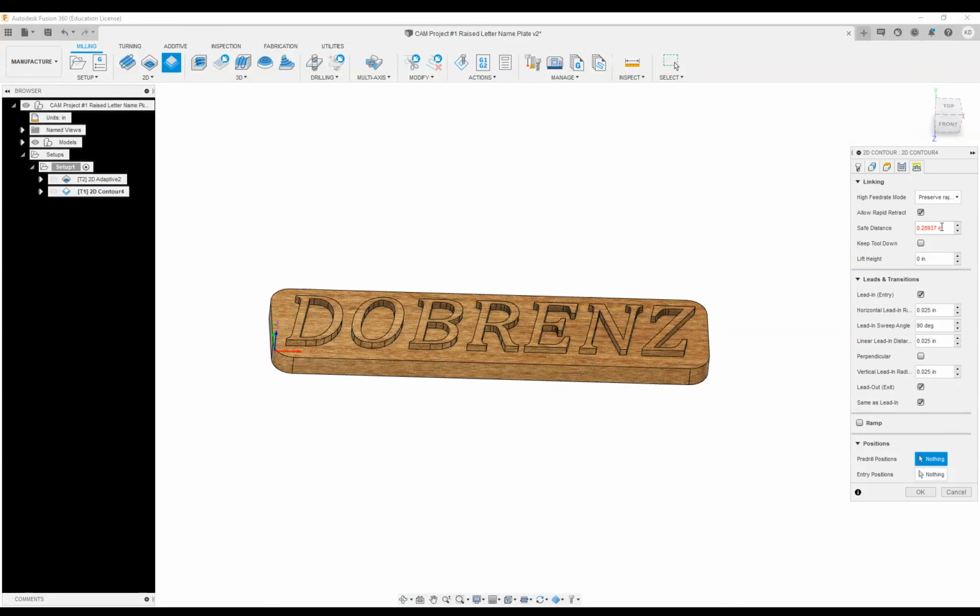I have some red here that I know I need to address, or I will have a problem. It won't calculate. So it tells me that this can't be any more than the height of the cutter. And it's still not liking that. What if I go just below? Now, let me do it. All right, I better read this then. Safe distance is higher than the feed height. Consider adjusting the safe distance, or it will be matched. This needs to be less than the cutter.